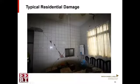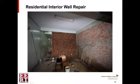This is a shot of some typical damage inside a residential space. So you can see it's just some cracking of some unreinforced brick that's there. And this is a photograph of the repair that was in progress. We were there approximately 10 days after the earthquake. And that unreinforced brick is being replaced with unreinforced brick. So societal response is just to get their living space back fully functional without any regard to actual building performance. It was a little bit different than what we do here in the United States and in other locations.